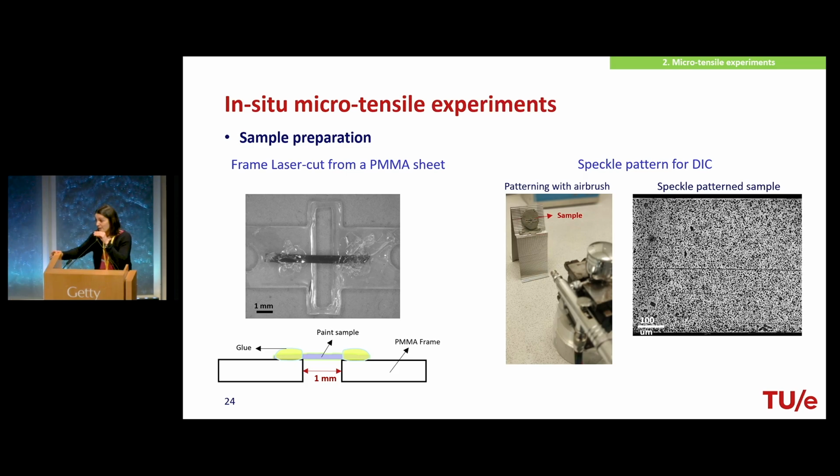We do also have a zone which we call the transition zone, which is very thin because we consider this to be the reaction zone, in which we have the two phases existing at the same time. Once it crystallizes, we assume that the reaction is irreversible. But in this reaction zone, we do have amorphous metal soap and crystalline metal soap at the same time. So this is also consistent with what Joanna mentioned yesterday. I thought you asked me about cross-sectional observation of these, and on that I cannot really reply.